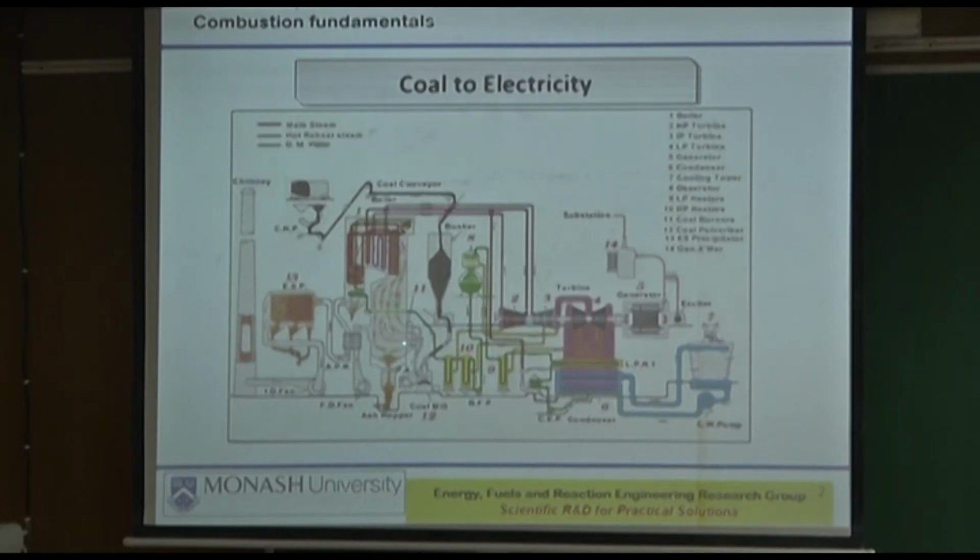This is typically the slagging zone of the boiler. This is where the superheaters are located. Subsequent parts are the reheater, and then the economizer, etc. And after that, the flue gas goes to the air preheater, whereby it gets cooled, but it gives its heat to heat the incoming air, both primary and secondary air, which goes in through the burners at different levels along with the coal, and then this is water. The rest is the steam cycle, so I'm not going into that.